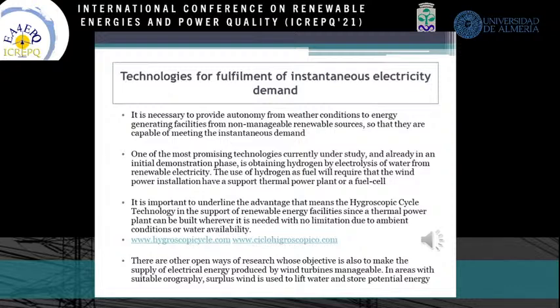This technology allows steam to be condensed in dry mode facilities independently of the ambient air temperature. We have experienced this in real conditions in Córdoba, Spain, at 40 degrees Celsius ambient air temperature. The efficiency of the thermal plant is increased by taking the steam turbine to the lowest vacuum it can reach.